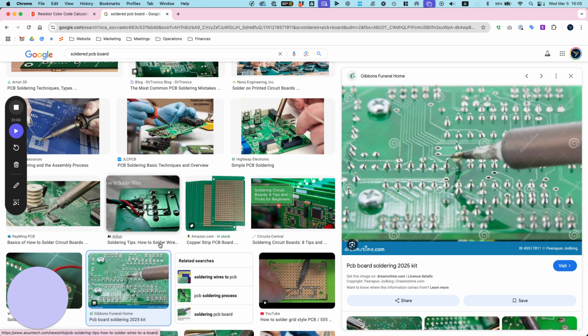Uh-oh. Okay, yeah. I bridged the neighboring pad for a moment, which is not good. Okay, there you go. Okay, there's a gap in between. I was concerned that between P and Q there was not. But you can always check with the continuity meter, or I'm going to just have a clean soldering iron and kind of wipe it off. To a certain extent, you can wipe it off.